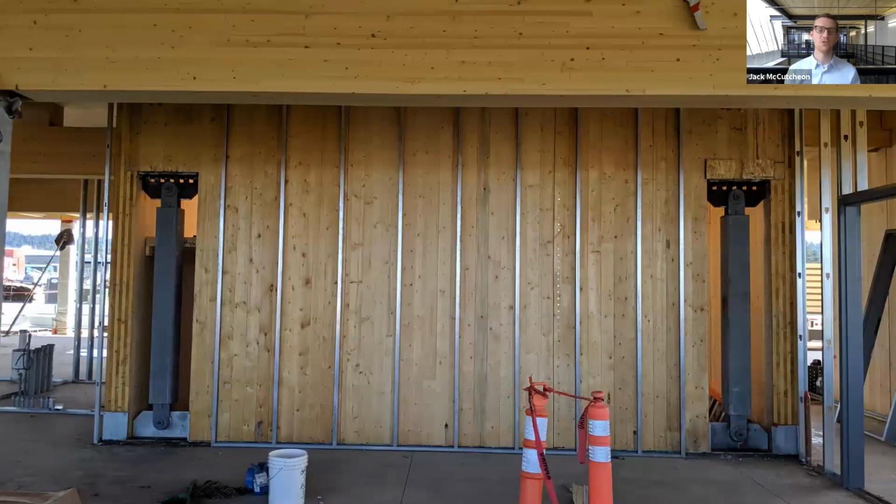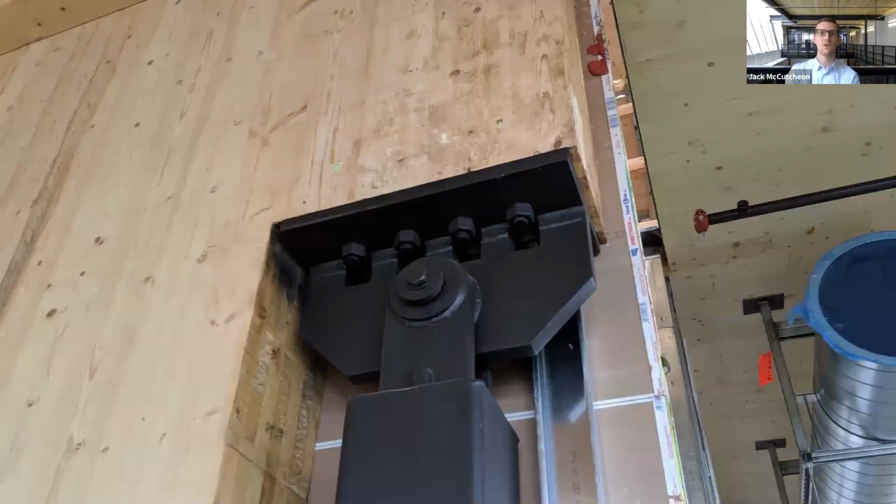Getting into some of the construction photos, here's a shot taken at the ground floor where we see the vertical BRBs installed on one of our cores. One of the tricky connections that we had to come up with was how the BRBs actually connected to the CLT shear wall. So we were able to leverage some of the connection testing that was done for the framework project that Reid's going to talk about,